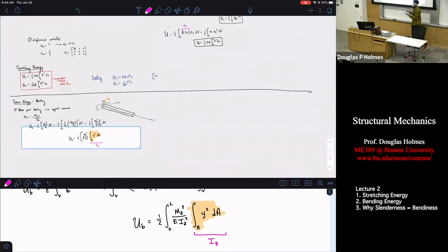I think this is sometimes covered in mechanics of materials, sometimes covered in statics. It probably depends on who you took it from and when you took it. But this is IZ. If you integrate over Z over the area, you get IY. And this is how you get the term everyone probably remembers, I being h cubed b over 12, maybe. It's because you're integrating over the two directions. You have a y squared, so you get a cubed. You have nothing for the other, so you get a b. But this is your second moment of area. You might remember that your first moment of area is the integral of y dA. So the second comes from the fact that this thing is squared. Anyway,